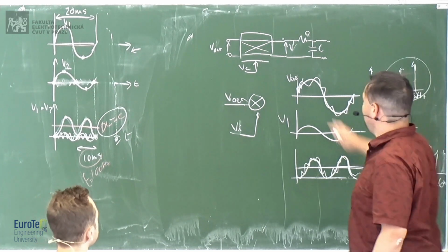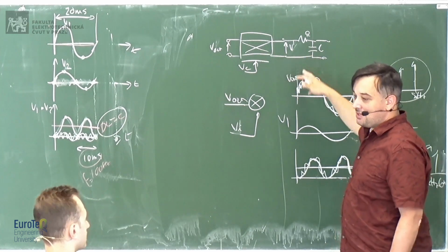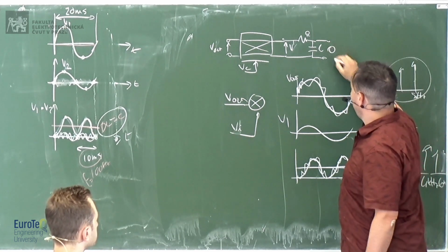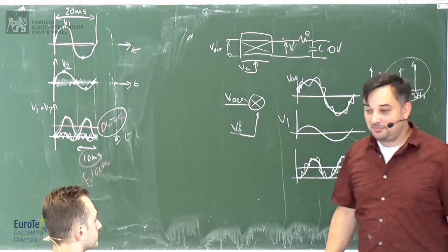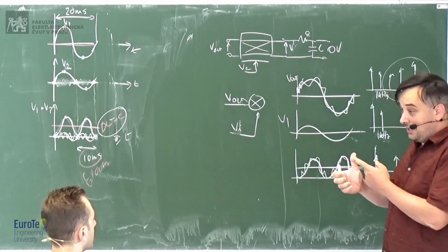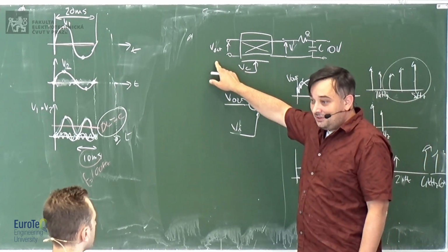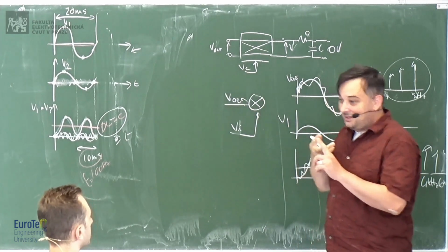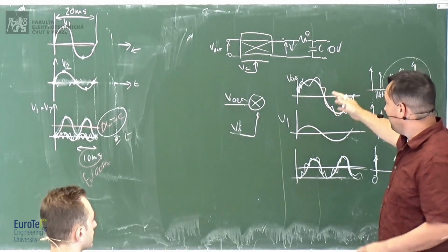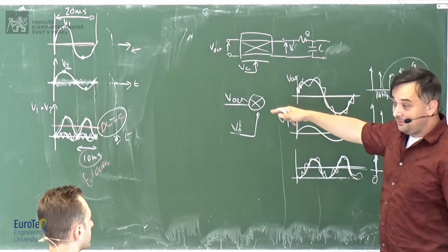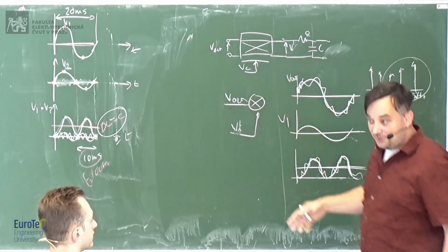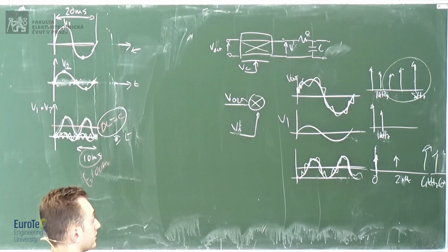Here you have an output which is V out times the cosine. You might say, let's say that we see 0 there, the DC value is 0 volts. Does it mean that it's purely imaginary? No, because it could be imaginary, or because V out itself is 0 volts. There are two possible ways, so you don't know. The only way is, if you want the real part of the voltage, use this circuit. If you want the imaginary part, you have to move the reference by 90 degrees, and then you see the sine.